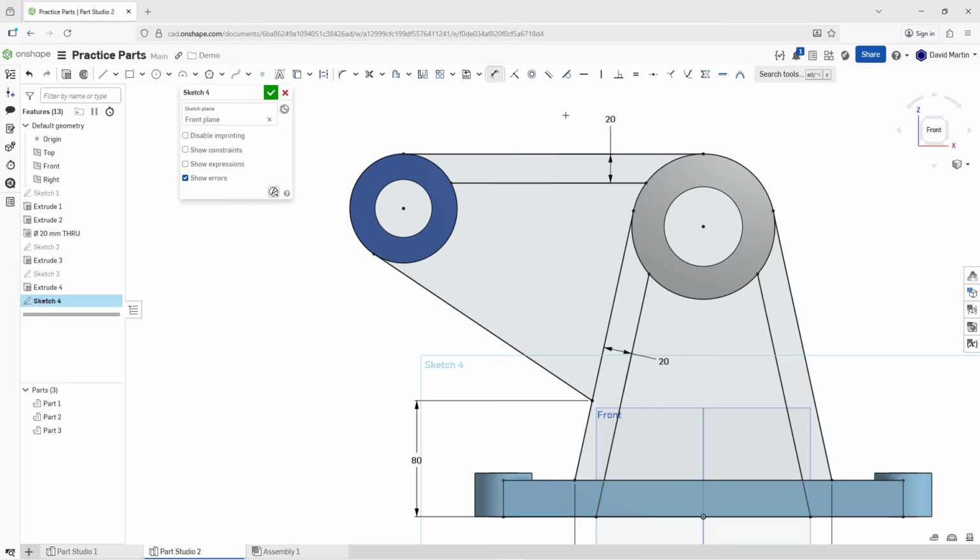And I think there's just one more entity that I need in this sketch. Let's sketch in a line, and let's see, will it snap to parallel? That's okay if it doesn't snap, because again, I can throw it in myself. Here and here, and then go to the dimension command, and the distance between these two lines is going to be a distance of 20. And that is good for the main sketch for most of the remaining geometry.